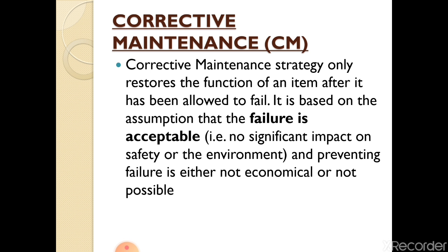Once the breakdown happens, the repairs and inspection follow. This is your corrective maintenance. As the name says, corrective maintenance occurs when there is a work stoppage because of machine breakdown. So the main objective is to get the equipment back into operation as quickly as possible in order to minimize the interruption to production, to control the cost of repair, to control the cost of operation of repair shops, to control the investment in replaced spare parts, which are called standby or backup machines, and to perform the appropriate amount of repair at each malfunction.